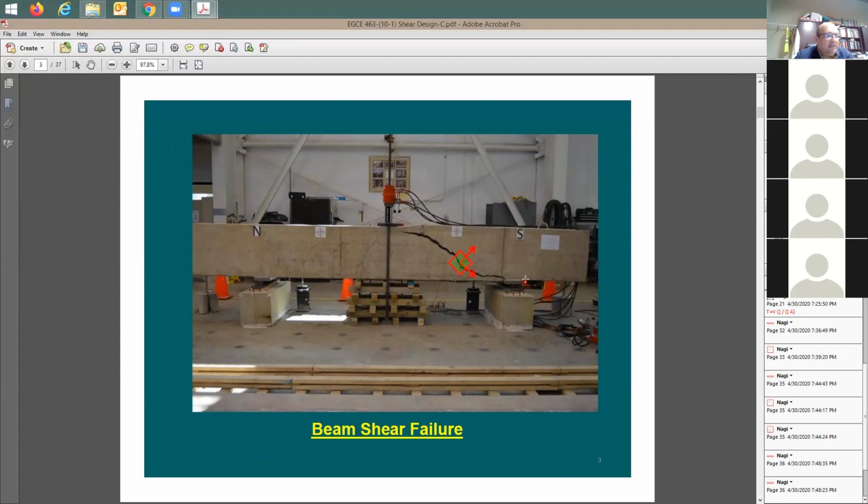Just imagine if this had been a pre-stress beam. So the pre-stress cable is going to be coming this way, which is good. You see where's the direction of the tension force? It's going to be coming like this, going in the same direction, which means this pre-stress strain that we put here is going to help in the shear. Number one is going to be closing all these cracks.